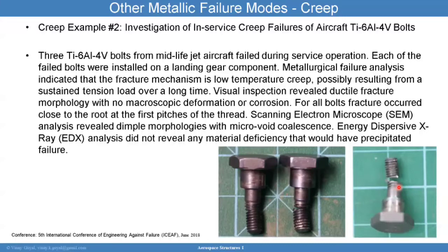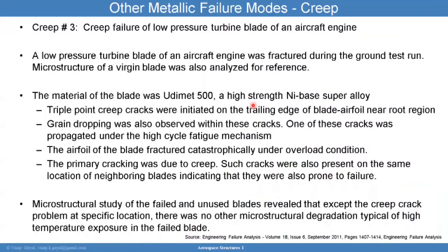And so when they analyzed the fracture surfaces using a scanning electron microscope, also known as SEM, the analysis showed microvoid coalescence. And so that is a sign that this creep mechanism could have occurred. Now, the EDX analysis, energy dispersive X-ray, did not reveal any material deficiency other than this mechanism related to creep.